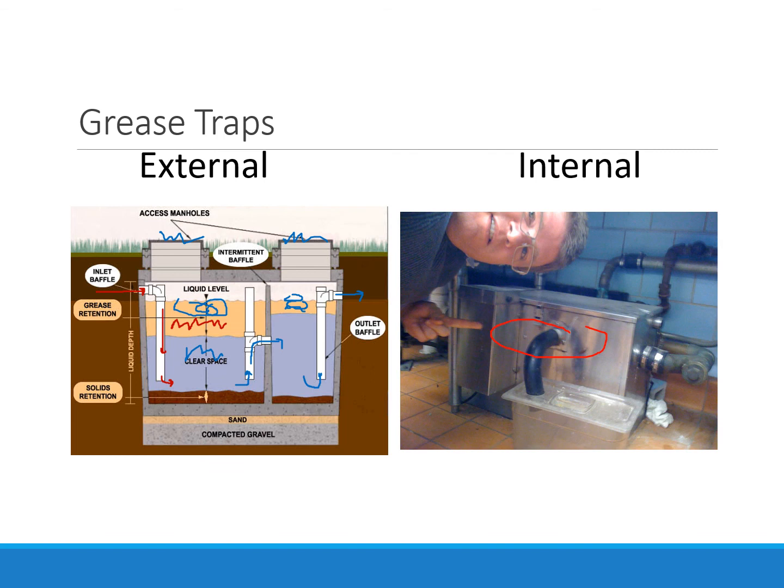And the baffled area where the grease collects is this thing down here. So when this fills up, you go out and dump it into your grease pit or wherever you have to dispose of grease. But let me tell you, this thing down here smells terrible when you open it. So whatever you do, pay somebody you don't like to open that.